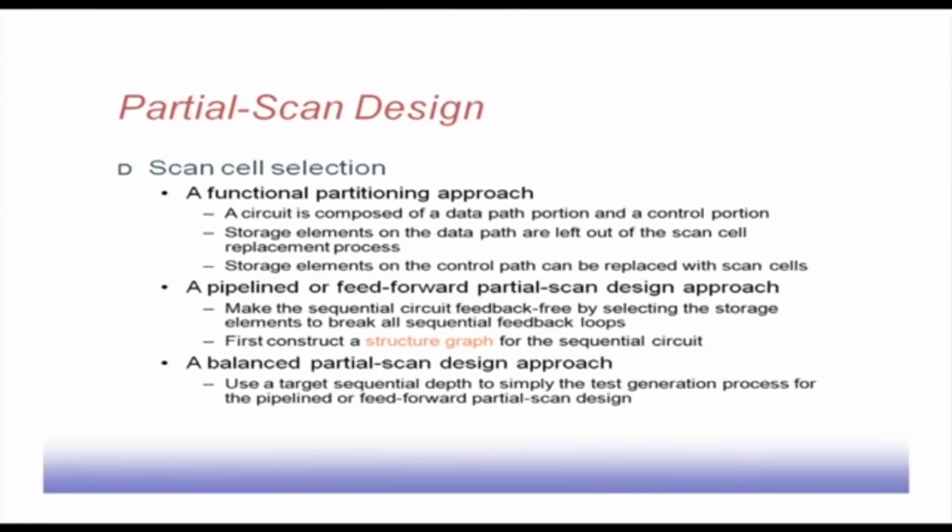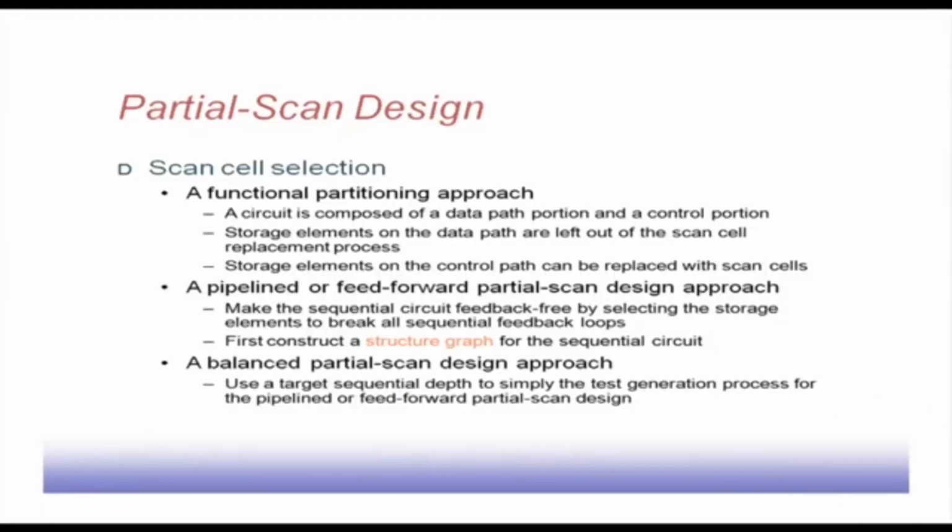Now, the question is that in my design there may be a number of flip flops or number of latches. How do you select those sequential elements that must be put onto scan cells, or converted into scan cells? So, the first approach is a functional partitioning approach. A circuit is